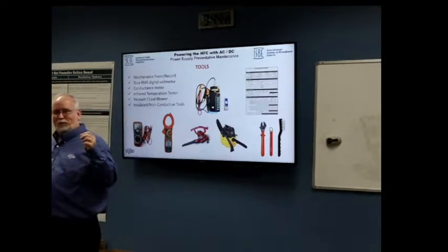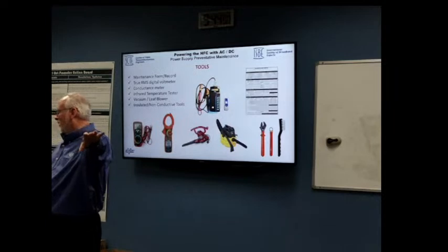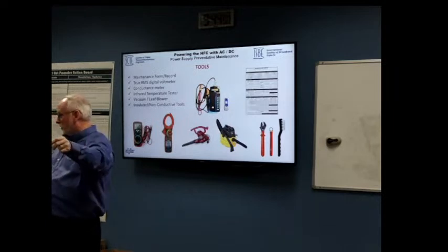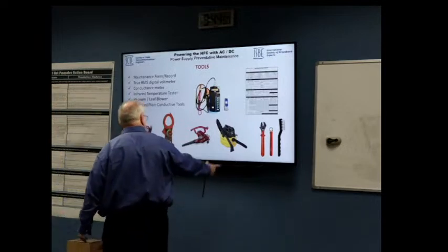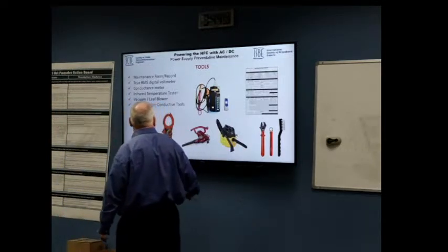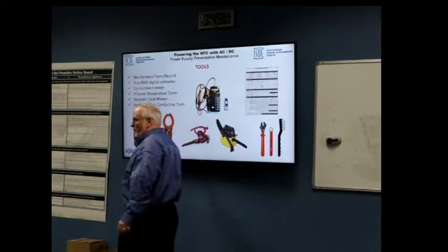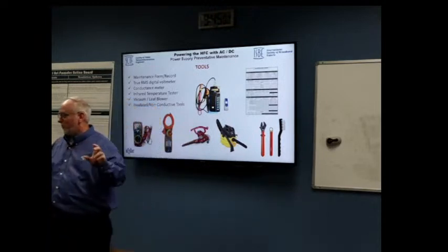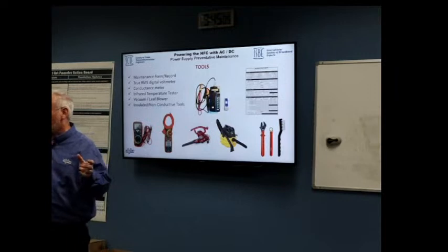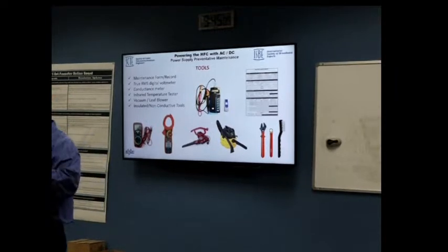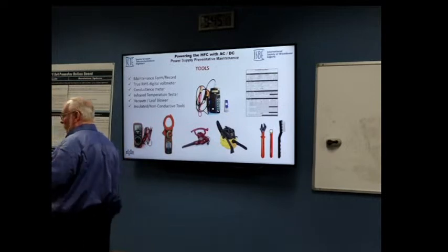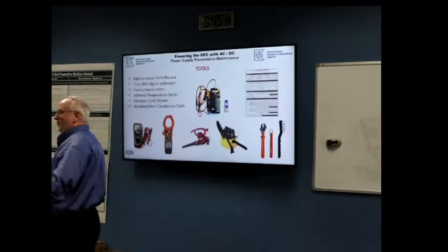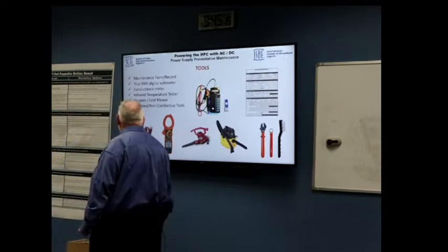For some reason, we just provided as little space as we could in the bottom of that cabinet to work on those batteries. Now you can pull them out if you've got a slide-out drawer, but an insulated wrench and a socket set is always good. A blower is good for two reasons. One is to blow out the cabinet, part of SCTE 205-2014. Make sure the cabinet is policed. But it's also good for chasing out mice and snakes and stuff like that from a distance.